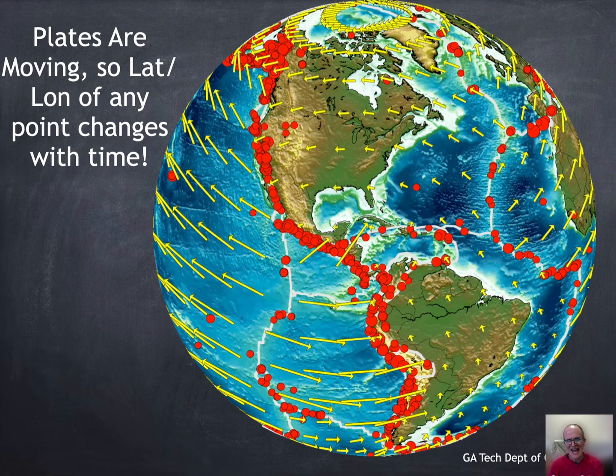We just thought the Earth was static and erosion maybe eroded away the surface, but we didn't really think that plates moved around. But by the mid-1960s, enough data accrued that said, nah, these plates are moving. And that changed how geodesists thought about how we had to measure things. And really, it complicates our lives because it's really the latitude-longitude grid with these continents moving under it. So we had to come up with a system to fix that latitude-longitude grid that was independent of measurements on the surface and then measure to the stars. And so that's where this VLBI idea came along. And then using the GPS to measure a denser set of points.